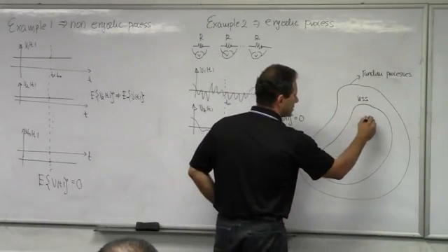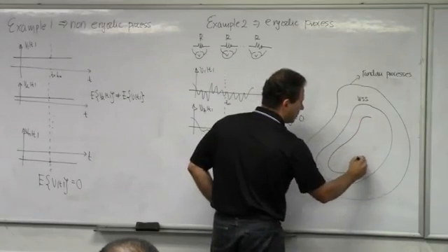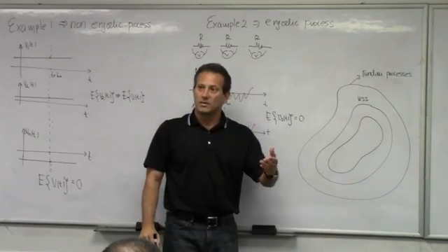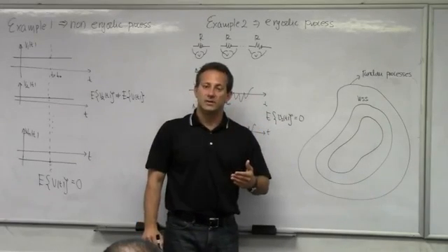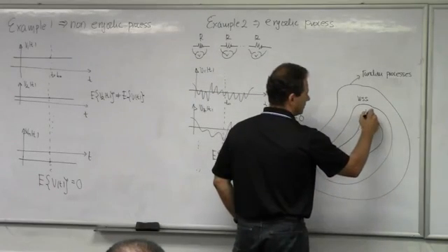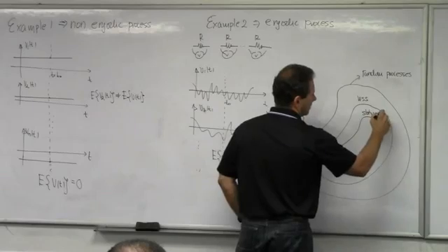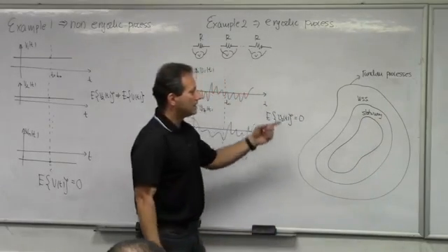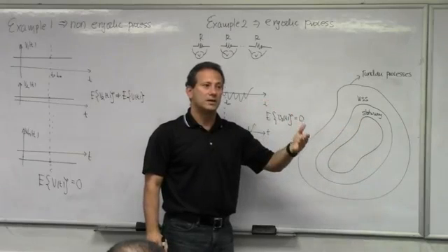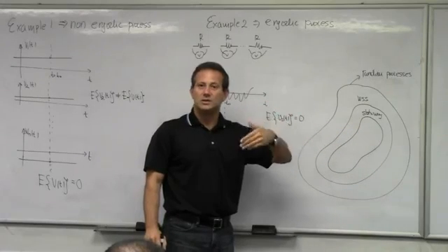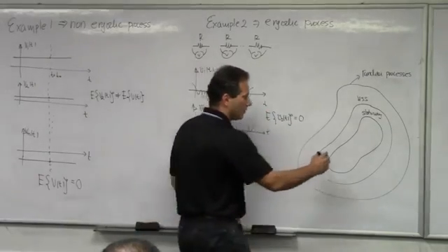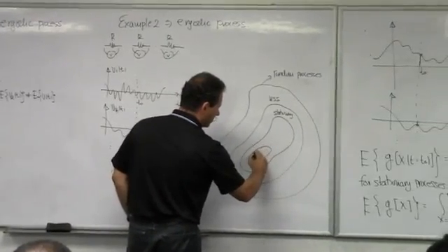If you have a wide-sense stationary process, but not only do the first two moments not change over time, the entire PDF does not change over time, then you have what we call a stationary process. Strictly stationary. And then a subclass of the stationary processes, for which I can obtain the averaging either in the ensemble domain or in the time domain, are called ergodic. So these are my ergodic processes.